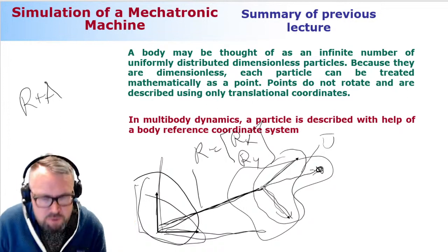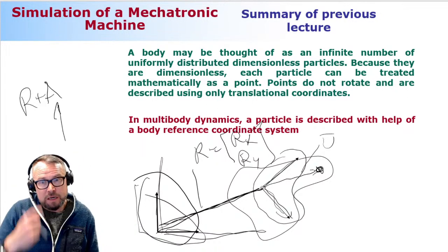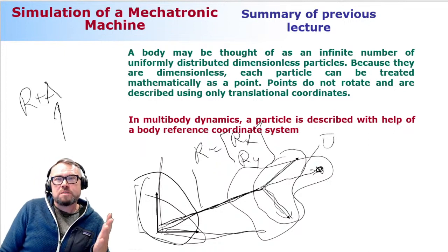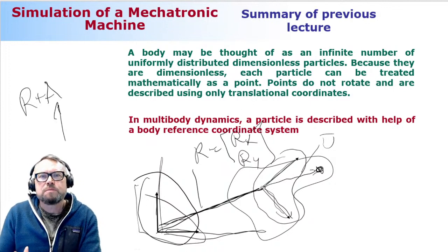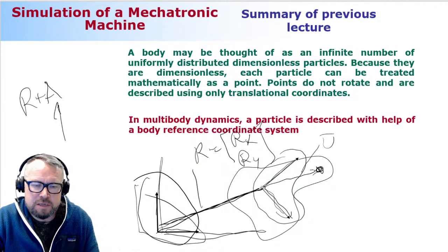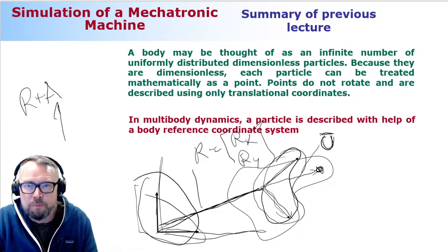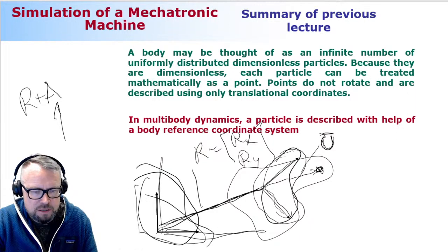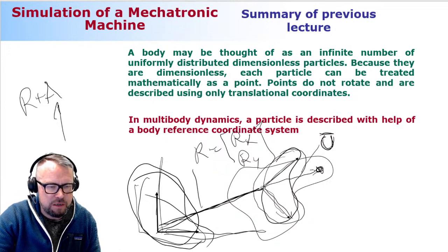Yeah, so I was about to explain this 2x2 rotation matrix, which maps representation from body coordinate system to global coordinate system. So what this means for us is that we can convert this vector u bar, which is initially expressed using this coordinate system, to be expressed using this global coordinate system. Let me change the color to make this a bit clearer.